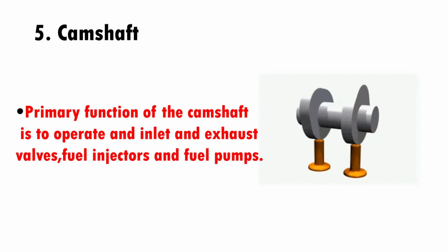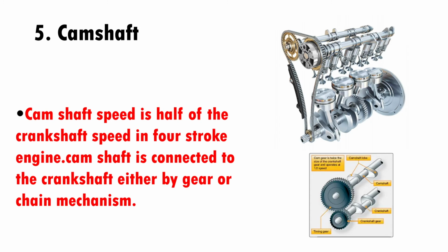Camshaft. The primary function of the camshaft is to operate the inlet and exhaust valves, fuel injectors, and fuel pumps. Camshaft speed is half of the crankshaft speed in a 4-stroke engine. Camshaft is connected to the crankshaft either by gear or chain mechanism.